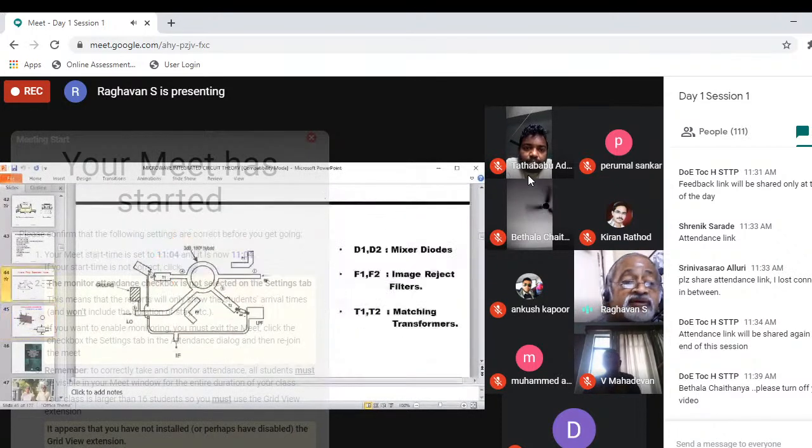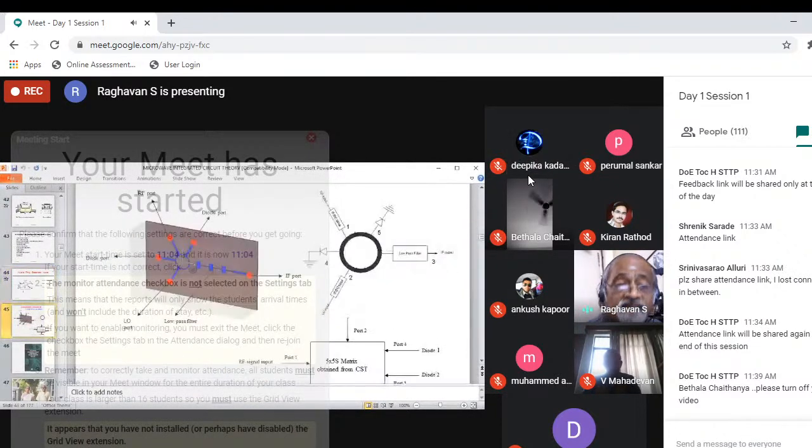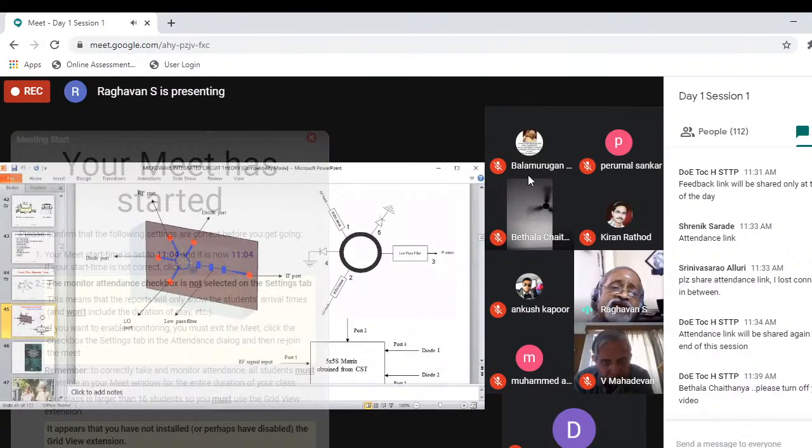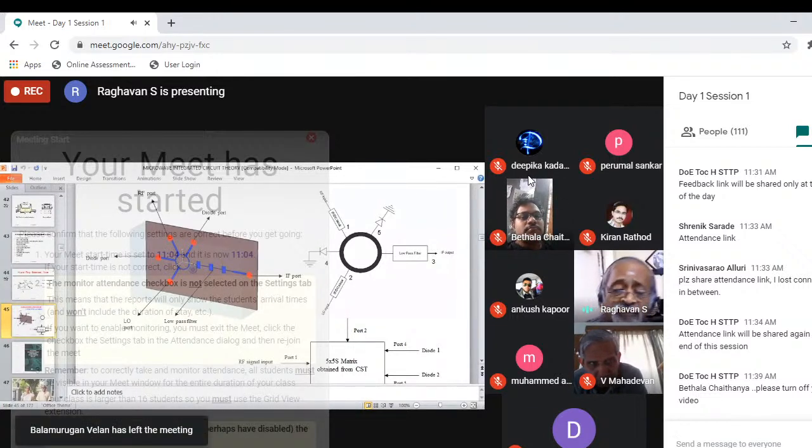Whatever I have shown has been realized in microstrip form, in stripline form. This is the layout. You can just transform it into the form of a microstrip or stripline, or any other planar transmission line, according to the principles. Now you can see the low pass filter is there, local oscillator is there, RF port is there, diode port is there, matching is there, output port, everything is there. You can minimize it, so you can make it in millimeter size, micro size, or whatever it is.